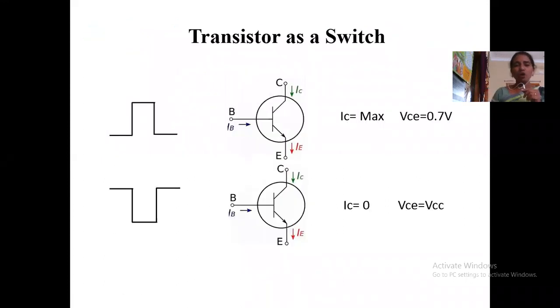To understand the operation of the monostable multivibrator, you have to know about transistor operation. When we give a positive signal to the transistor in common emitter configuration, the transistor starts conducting and enters saturation. In saturation, the current through the transistor is maximum, and the collector to emitter voltage, VCE(sat), is approximately zero. So when the input is positive, current is maximum and voltage is minimum.